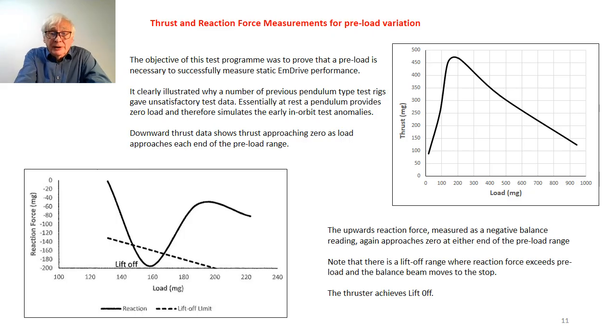We confirmed this by doing a set of reaction force measurements, which is the plot to the left, and you can see there that again, at each end of the load range, in this case a much smaller load range, you see that we go from 0 up to a negative peak and back towards 0 again as the preload is increased.